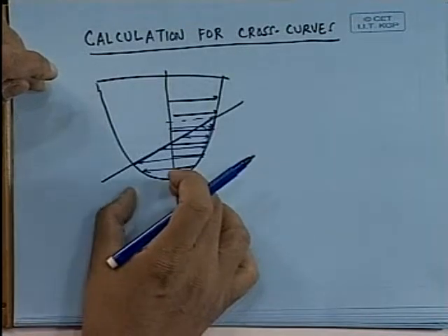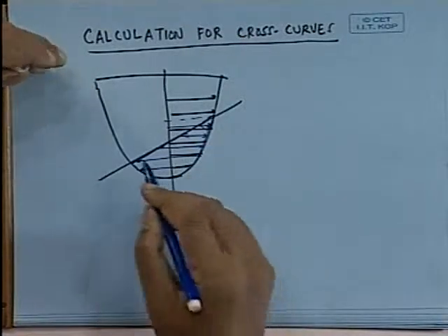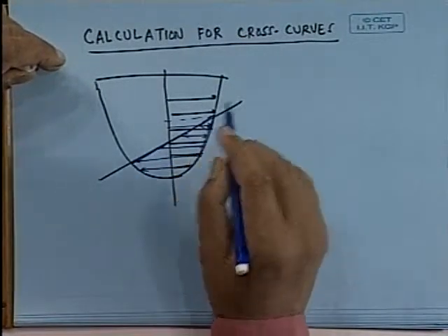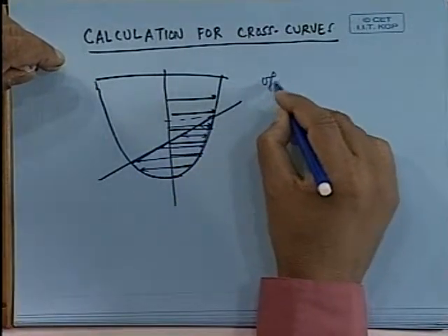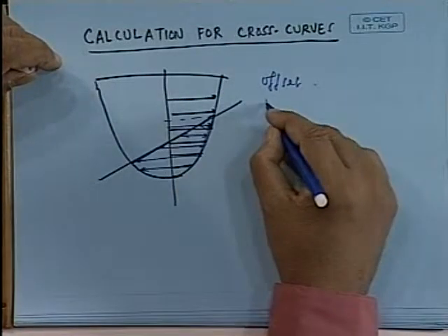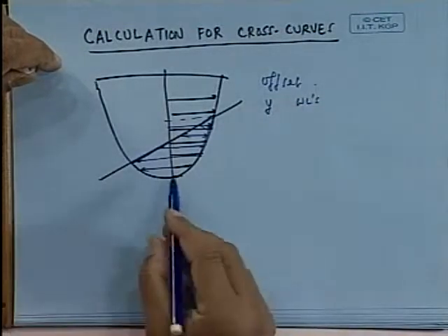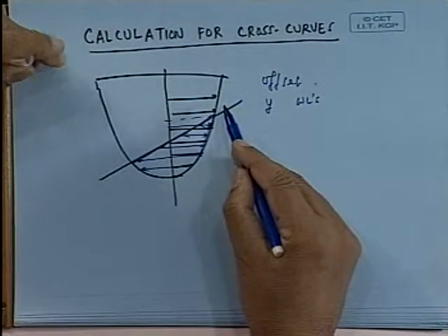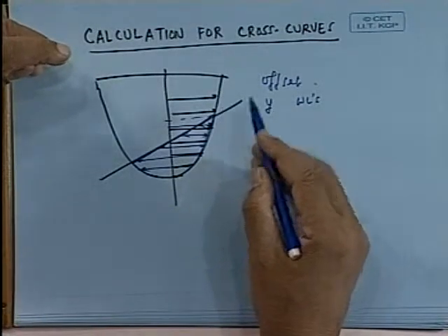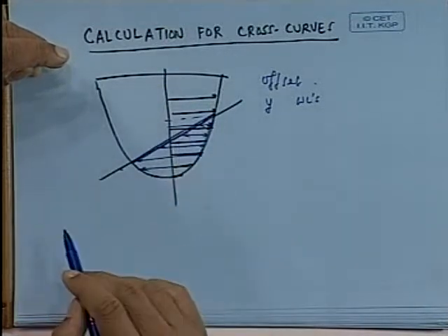Now again, for each station, normally I have an offset. What is an offset? Offset means I have y values at fixed intervals of water lines. But here that concept cannot apply anymore, because this particular line does not fall on water lines, first of all.